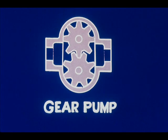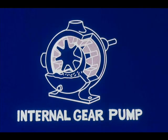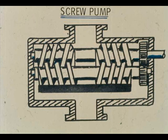Here is a standard gear type. When the liquid goes in, it occupies a comparatively large volume. But when the gears mesh, they reduce the volume the liquid can occupy and force it out into the discharge line. Here is an internal gear type. It looks different, but it works the same way as the standard gear type. In this screw pump also, incoming liquid occupies a comparatively large volume. The rotating screw reduces the volume the liquid can occupy and forces it out into the discharge line.